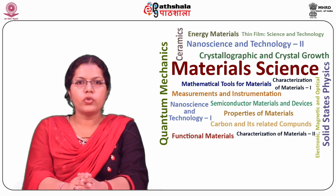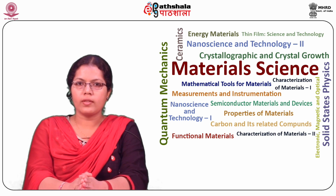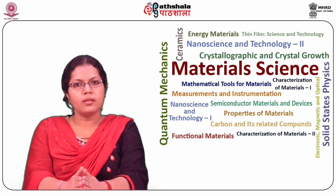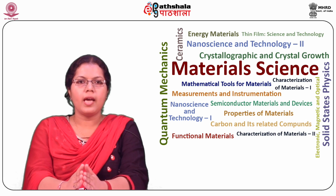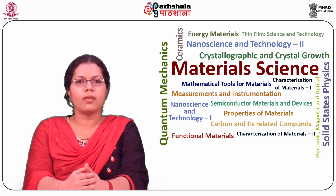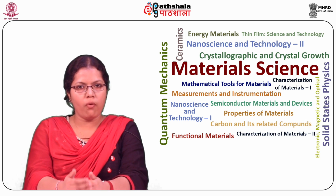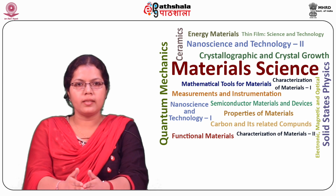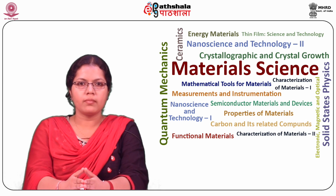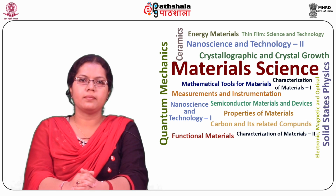The coils should use stranded wires, as otherwise the eddy current losses in conductors become large, especially at higher frequencies. The use of metallic parts should be avoided, as the eddy currents induced in them affect the value of inductance.